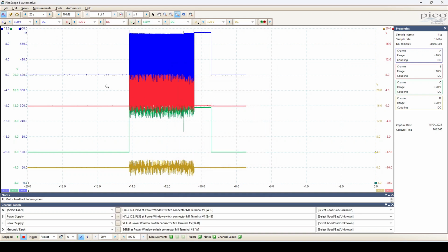And I want you to see the frequency here. So let's take this up. You see in this area here, this is where I put my hand in. The window is going up fine, it's a constant velocity, and then suddenly the computer senses, hey, the velocity is dropping. When it sees the velocity dropping like this, the frequency drop, it immediately knows that there is some kind of obstruction and reverses the direction of that window.